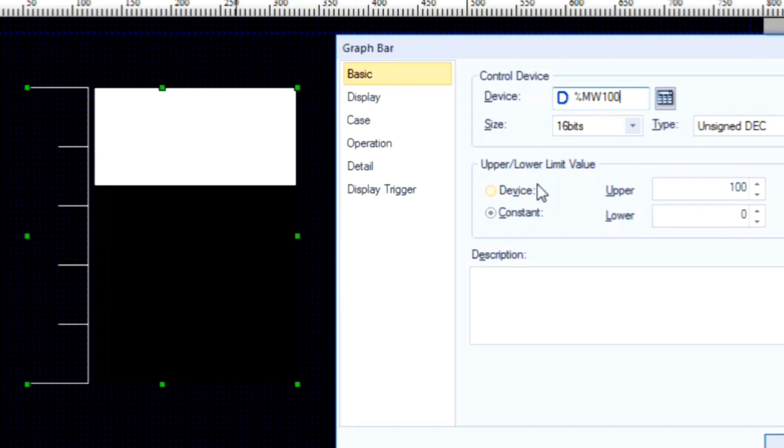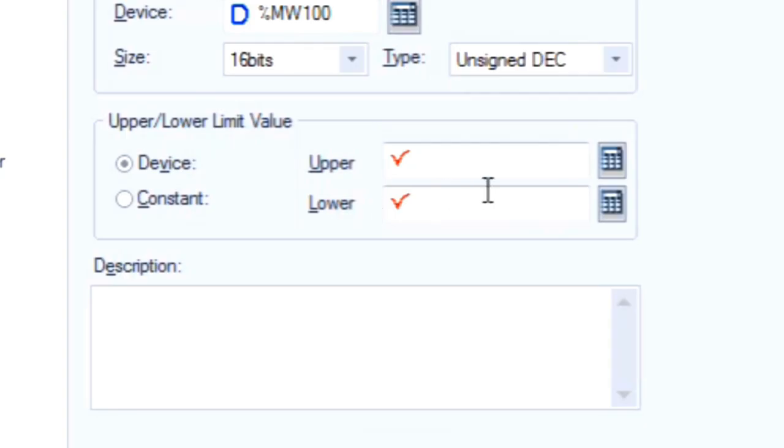Or, for example, we could add two numeric inputs in the HMI, and depending on the situation and the various technical processes that might occur in the system, we can set the upper and lower limits ourselves manually. If I configure these settings directly on the device, we can assign one starting address for the lower limit here, and then a separate address for the upper limit.